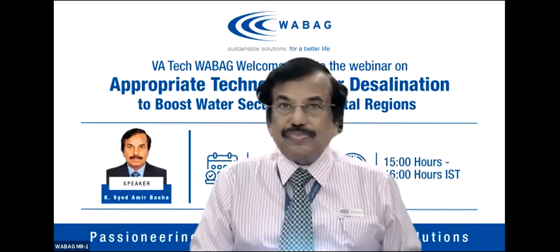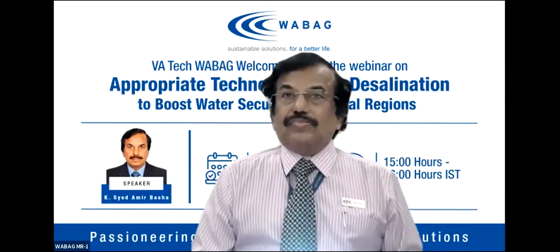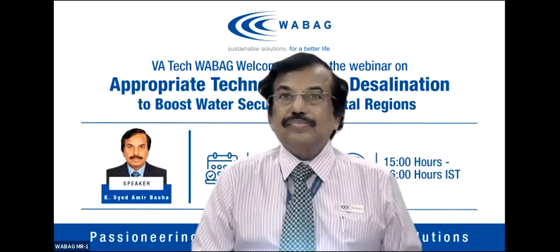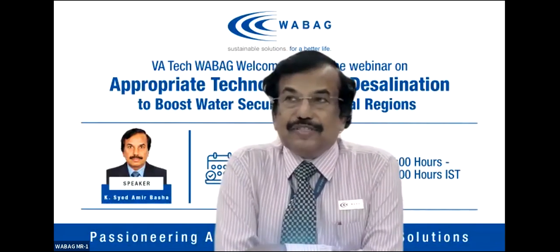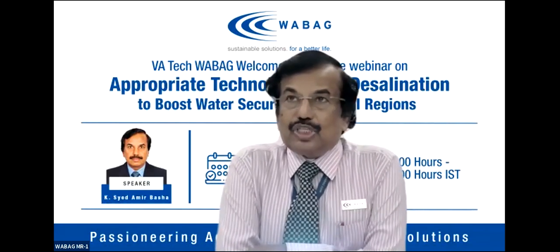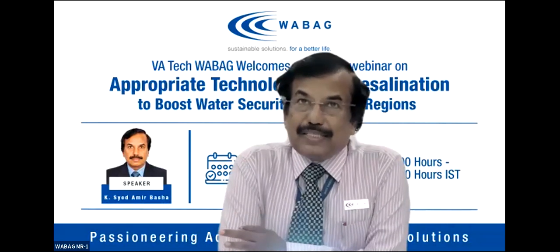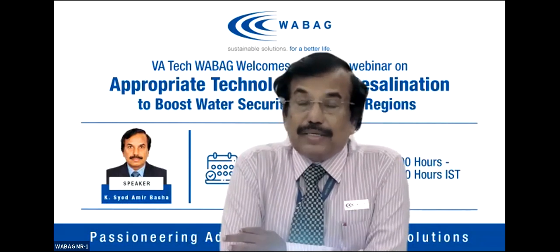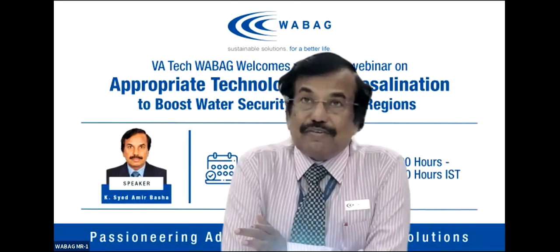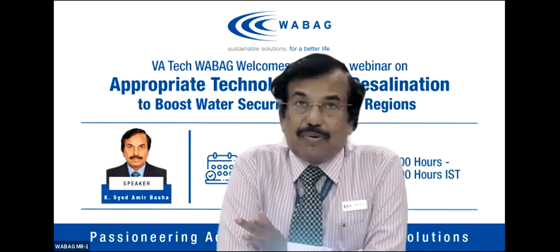The next question is from Mr. Balasubramanian. Considering the UF membrane cost and high maintenance involved in the UF system, can we avoid the UF system and focus on the RO system? Yeah, the necessity for a UF system depends on the seawater quality. If your seawater quality is good, you can go ahead with the dual media filter itself or gravity filter itself. There are many plants running in the world with just gravity filters or dual media filters. However, I have also operated a plant with a beach well with just a cartridge filter. There is no other filter in the system. So it all depends on the feed water quality you get as raw water for the system.